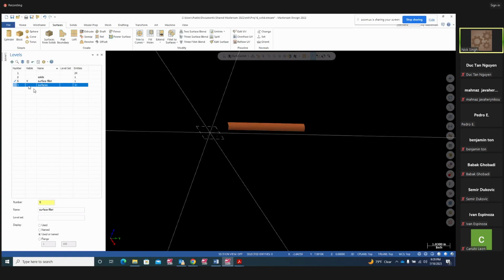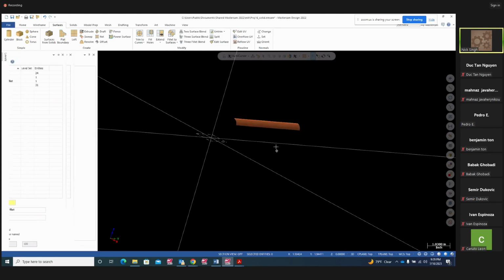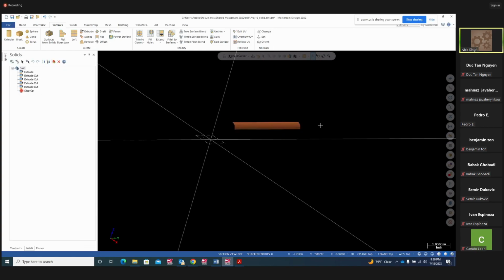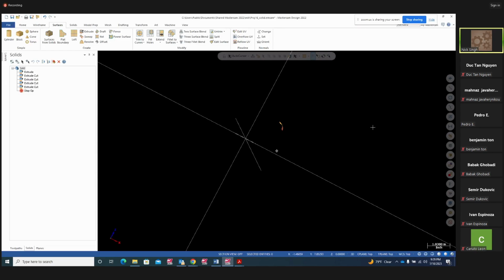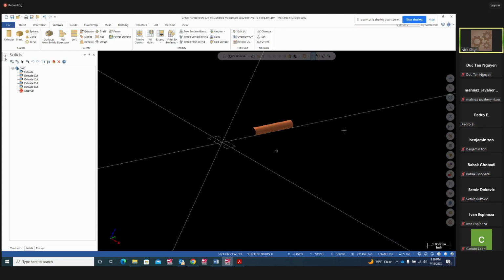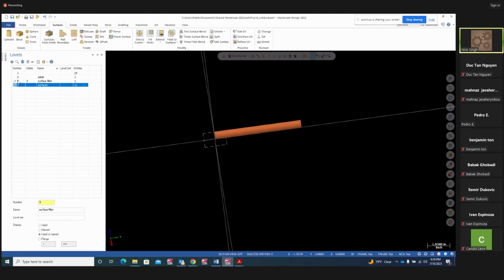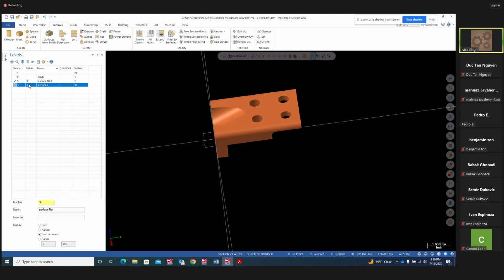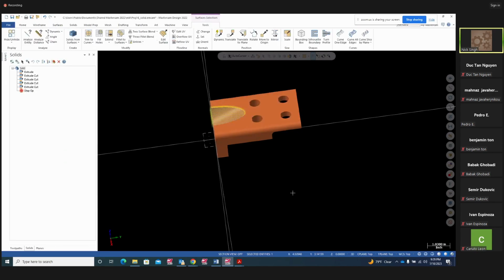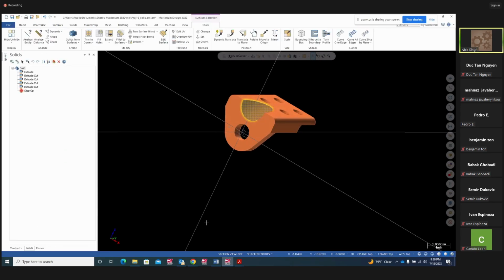You have your surface fillet and you can just create a toolpath on this surface. That's the beauty about surfaces. So any surface, click all surfaces, turn it on. You can pick any surface you want to work on. You want to work on this surface, put it at a different level.